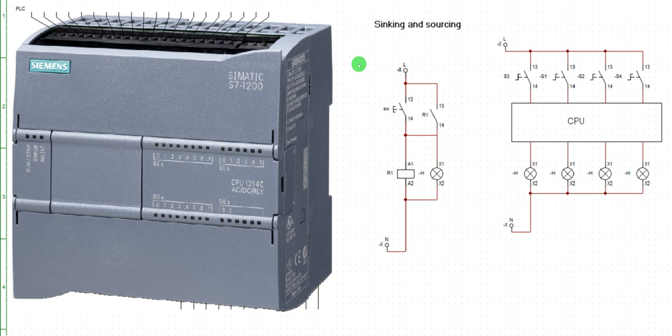You understand me? You get the point now. You know the magnitude of 1000 amperes. The CPU does not carry that load. The current carrying capacity of that particular load demand does not bounce on the PLC. The PLC just flashes the command. The other different panel with other components, contactor, and all the rest will take care of that load.